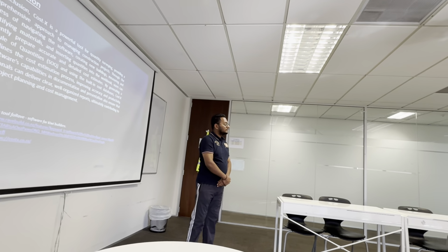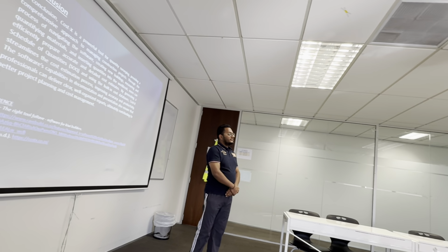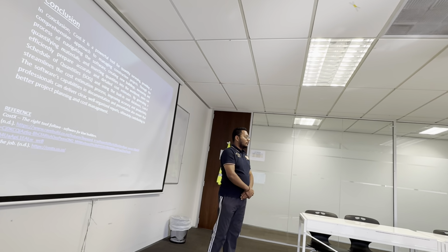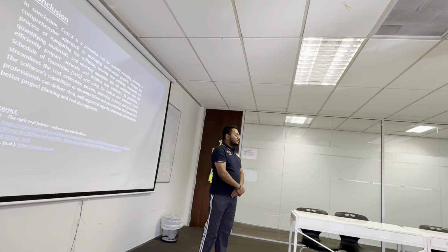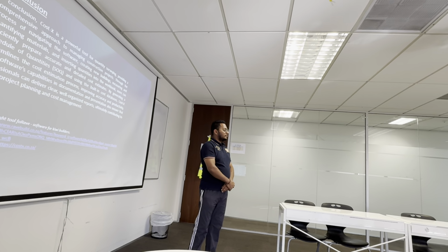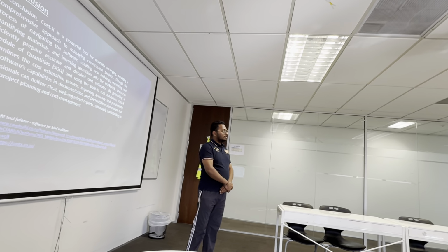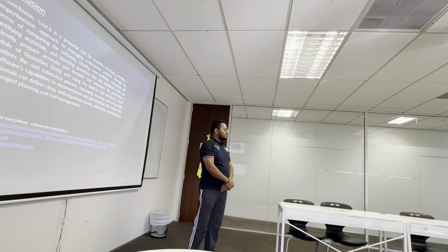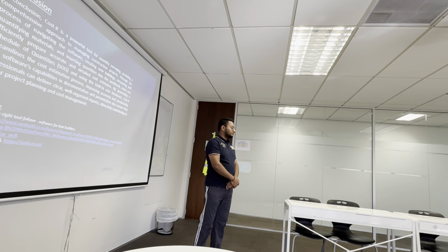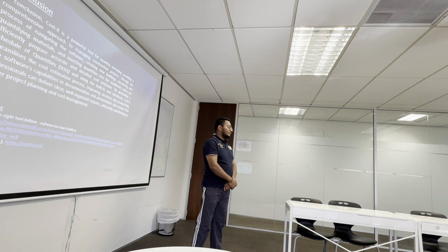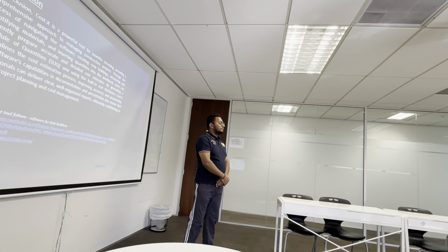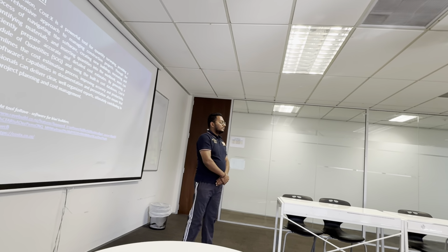After you insert the drawing, what do you have to do? After inserting a drawing, firstly we need to select the pages and then we need to measure the scale. If the scale is not correct, we need to use the x-axis calibration to measure correctly. Tell me what four trades you are dealing with in your program. Four trade sections in your SOQ.